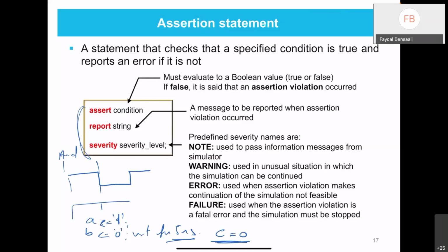And then the simulator will do the simulation, will use your VHDL code with your test bench. And if it gives an answer of 1 instead of 0, then it will show you an error in the message box down there, where you see the warnings and the errors when you compile.